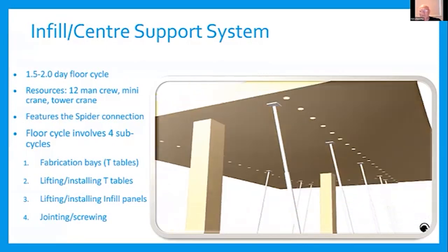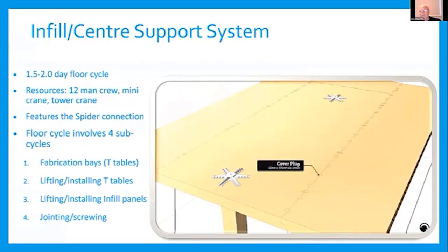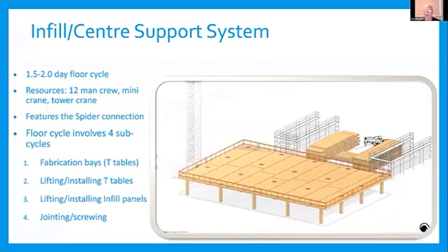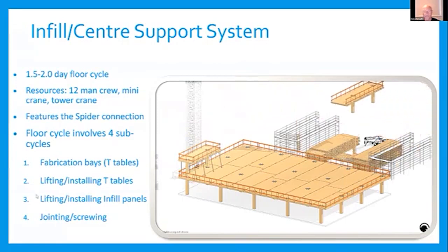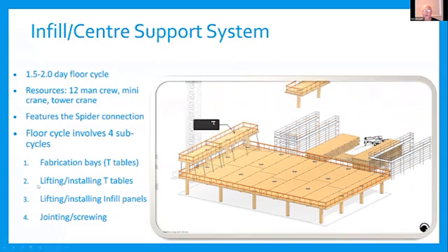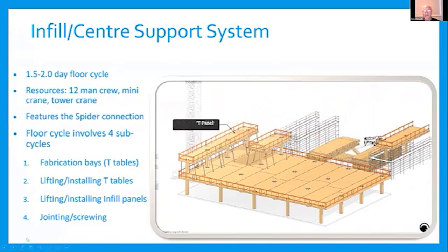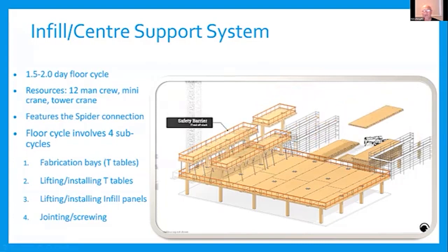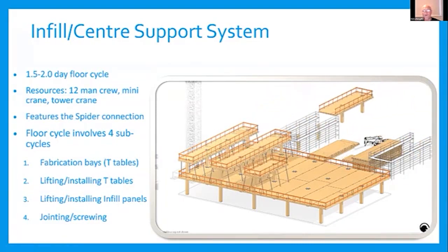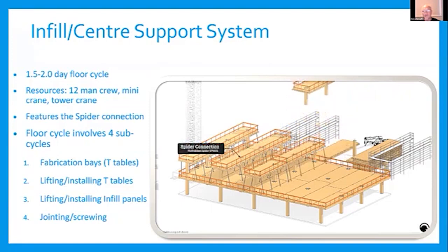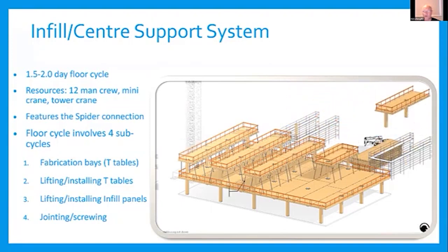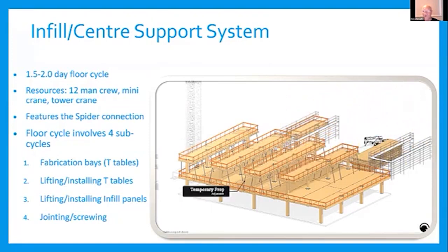So for us, it meant we'd put a team in early underneath because they're working in a safe area with edge protection, whereas we had to wait a bit longer for the top team to get on because we need our edge protection in place. We need to put edge protection around every single panel, as you can see, every T-table, so they could start putting in the spider connectors without having to wait. But once we got to a certain point, when the infill panels are placed, which will happen in a second, we were able to start